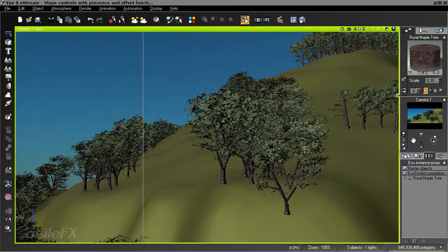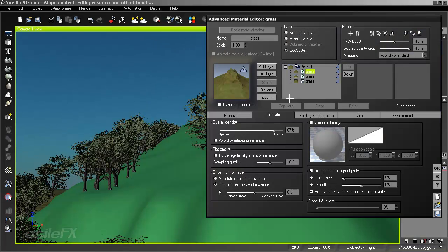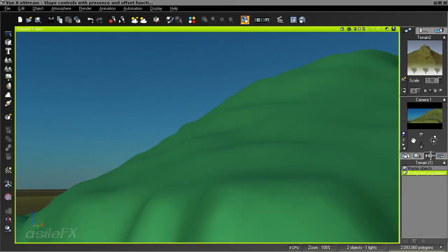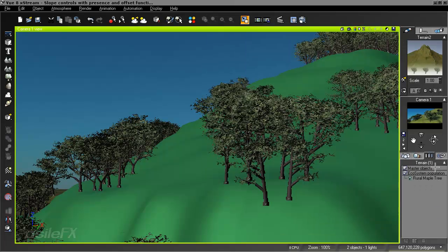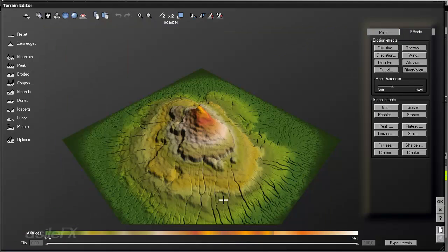To avoid this, because that is a really useful tool, I'm thinking that it may be caused by the fact that there's another layer with nothing on it. So I'm going to go ahead and delete the other ecosystem layer, clear out the population completely. And of course, with a cleared population, we can't access the object. So we'll keep the population on. Let's go ahead, and I am going to enable master object addition modes. Select the object, and it should show in the scene. So we're going to edit the object that way.